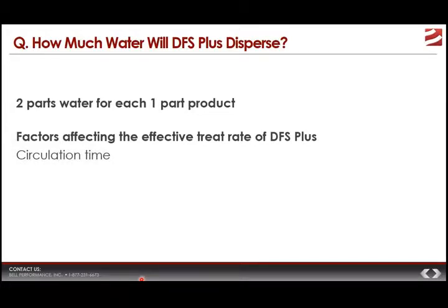How much circulation time? You might have a large tank and you have a certain amount of water in it, so you put the recommended amount in, but if you don't circulate it for a long enough period of time, it's not going to contact the water as well, and it may appear to be less effective. So circulation time is important.